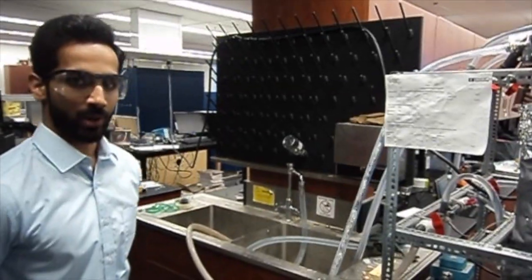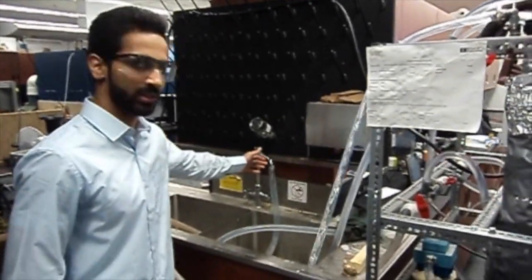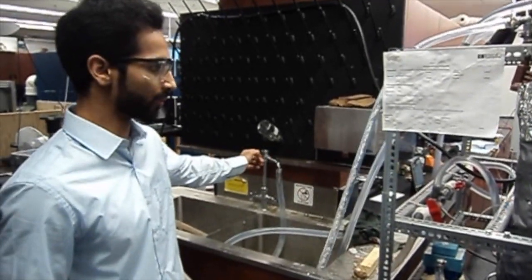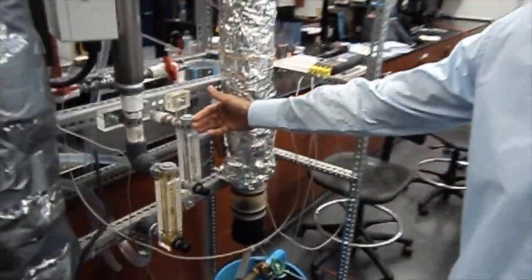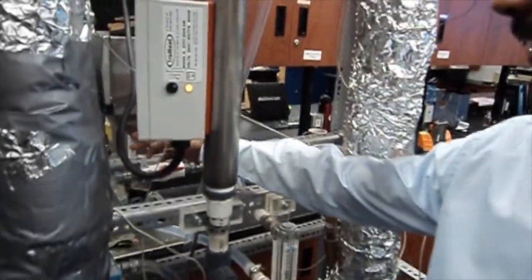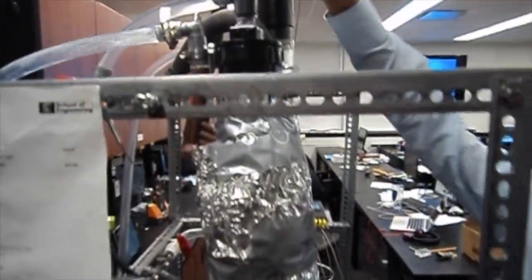and that's the closed loop. Now walking through the cold water loop, we have the inlet which comes in from the sink. This is the inlet to the house from the city. It goes here to the cold water flow meter. Now once it goes to the cold water flow meter, it goes past a couple of valves into the cold water inlet on this side, and then it rises up in a helix around the heat exchanger to the top here. And here it goes to the drain.